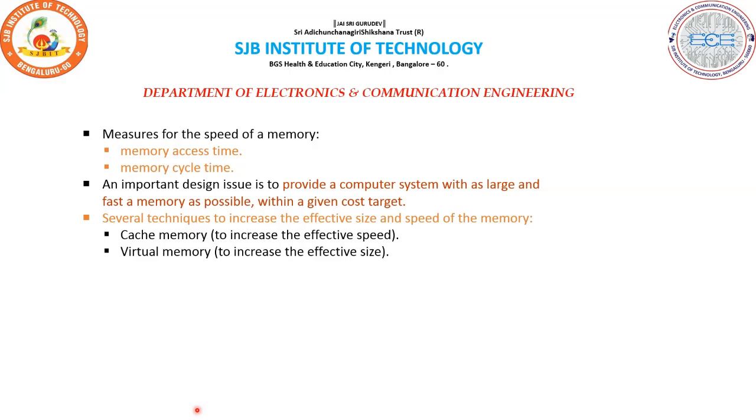For example, the read operation is initiated by generating the read signal, and another signal goes high, that is the memory function complete signal indicating the high signal. This is referred to as the read and the MFC signal. When the MFC signal goes high, then it completes the entire duration. That is known as the memory access time.